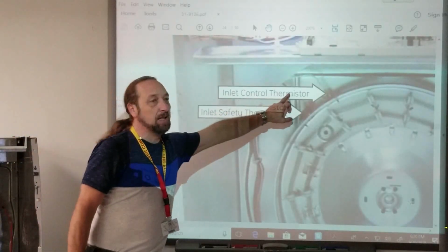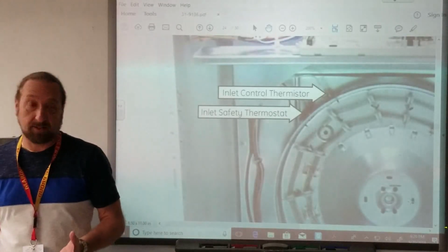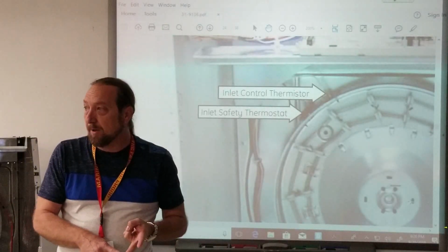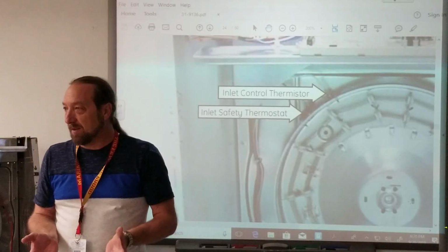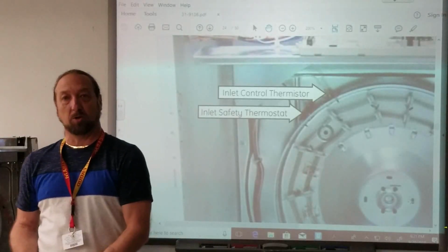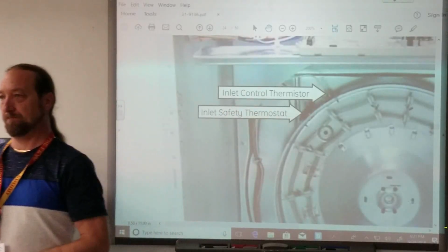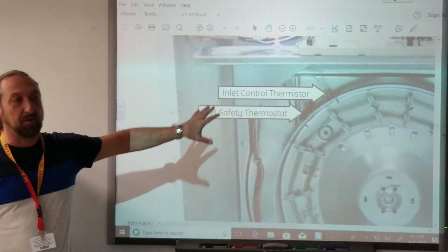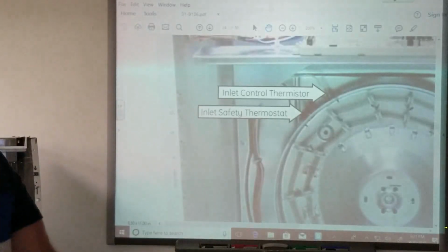And whenever we have an electronic controlled machine that has to do with temperature, and a majority of our machines now all do that. Dryers, we have to heat the air. Washing machines heat the water. Dishwashers heat the water. Ovens heat the oven, refrigerators. You have to have sensors that tell these control boards what is the temperature, because we can't get too hot and damage the clothes, or not hot enough and not dry the clothes. So a thermistor is talking to the control board, and a thermostat is actually turning something on and off, like a light switch. And we'll identify these components, okay?